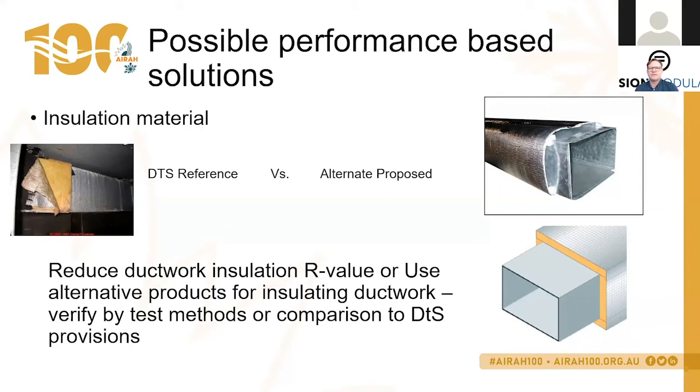You may reduce the insulation requirement locally at the pinch point. But any of these things are reasonable options to consider. So going through your duct design and duct solution and looking at those specific pinch points, you have options, and it's just a matter of going through the design approach.